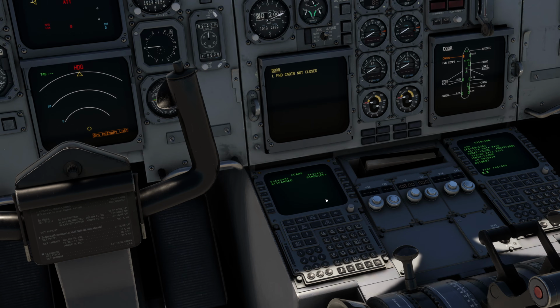In order to configure the MCDU, first of all, you have to go to this option Initialization, and you have to enter the departure and the arrival airport. OTHH/OMDB. This is the format that you will be using. Just press this button. Now, interestingly, this is something new, which I'm observing over here in the MCDU. It automatically gets all the waypoints and the airways. So you can see these airways are coming: L305, L305 to Idbol, and then M6, as I've explained it to you before, M677 to Dixam, and then M677 to Vutub, and direct to OMDB.